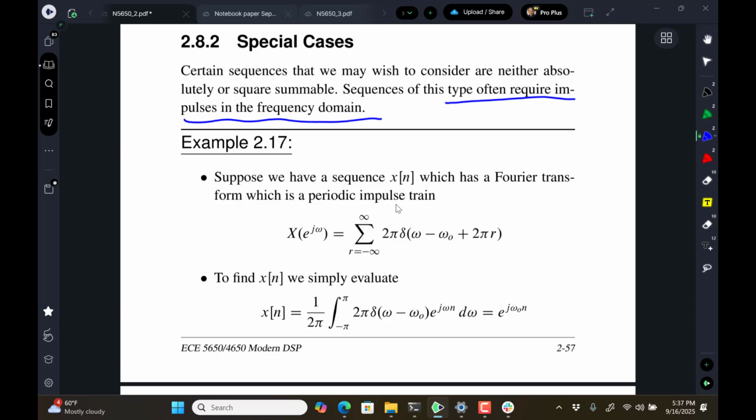Up until the relatively recent past, an oscilloscope was an analog measuring instrument, back in my generation growing up. Nowadays, an oscilloscope is usually digital, and if it has a spectrum analysis capability built in, like taking an FFT, then it has window functions and things like that to make that spectrum look more like the continuous time sinusoid spectrum, where it's a single delta function spike.